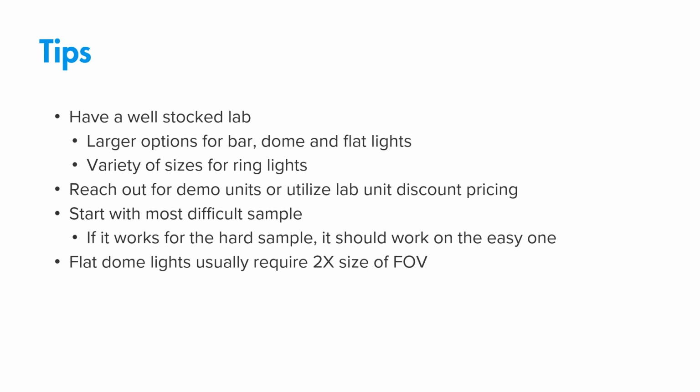Another tidbit of information, a rule of thumb, and we've said this before in other webinars: flat dome lights usually require 2 times the size of the field of view to get an even and uniform image. That's why we say larger options for flat lights, because they usually have to be pretty large, especially if your field of view gets pretty big as well. So keep that in mind when you're deciding what kind of lights you want for your lab.